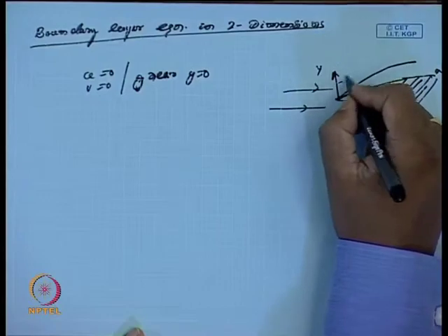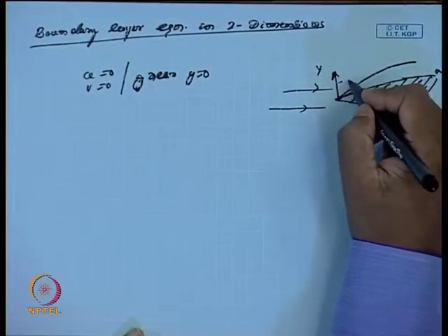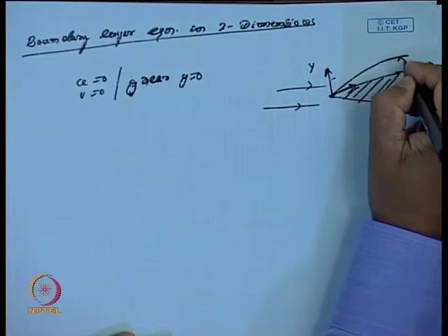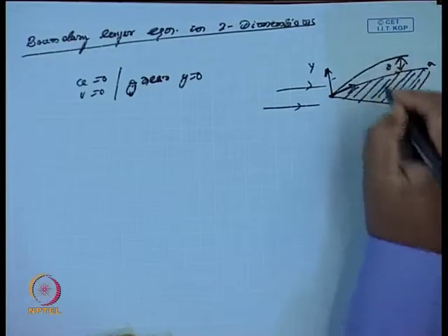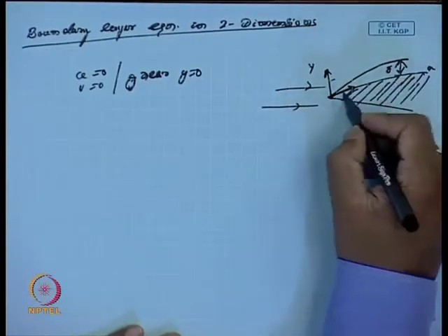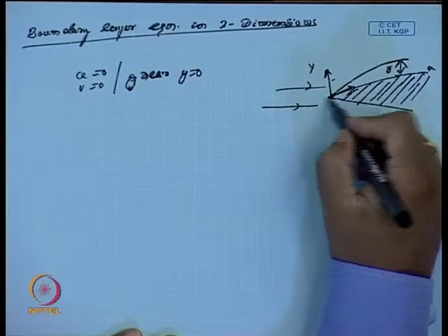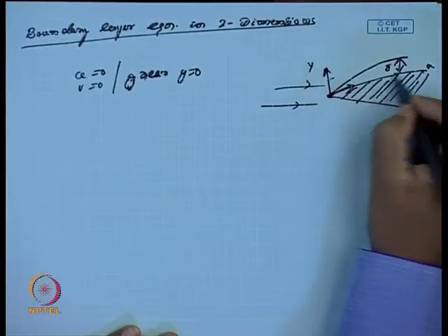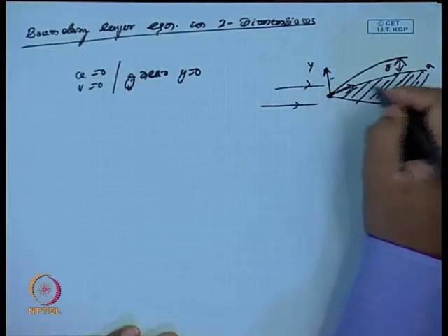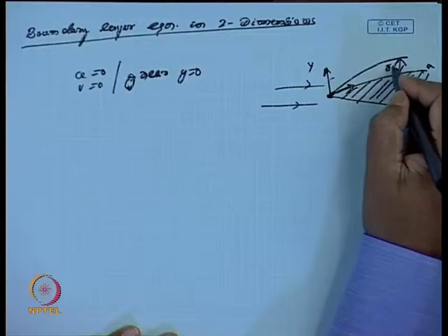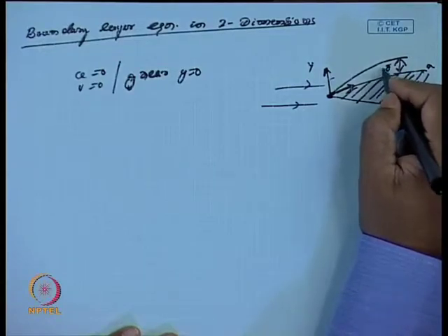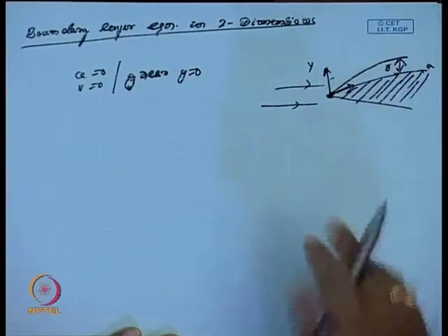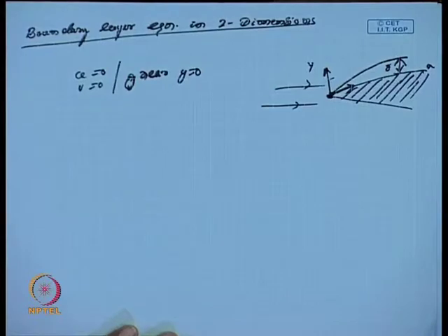So, there is a fluid flowing here. So, what will happen? Then this distance I call delta. So, what is happening? This is the boundary of a wall, there is a fluid flowing, the velocity at this tip is 0 and this is a rigid boundary. So, on the wall the velocity will be 0, but between this region the flow is called viscous, beyond which we call the flow inviscid.